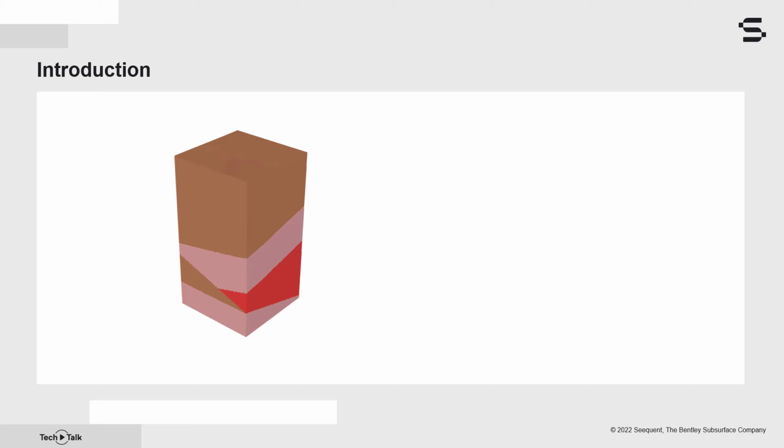The top brown material in our domain represents an ice-rich silt. The top portion of this can be considered an active layer where temperatures fluctuate above and below freezing over the course of a year. Below the active zone is continuous permafrost. Permafrost is a layer on or under the ground surface comprised of soil bound together by ice that remains frozen for at least 2 consecutive years. Below the permafrost is unfrozen ground. However, in this case, we will see that our domain remains frozen to the bottom.